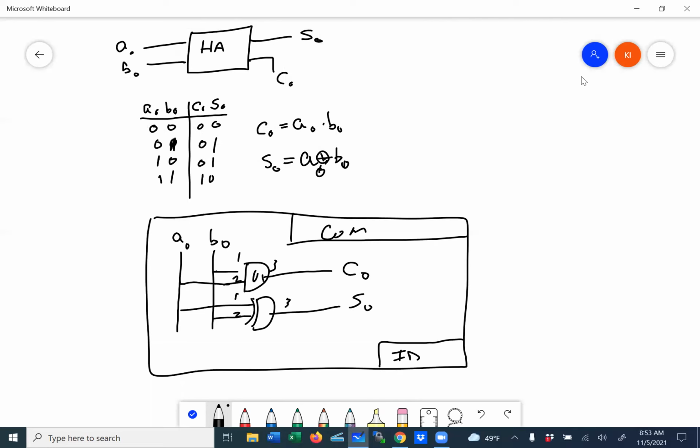And whatever, let's call this one U1 and U2. You're done. You basically have designed a half adder. You're done with that. The next step in the process is you do a full adder. Okay. And since now you know how to do a half adder, in the future, you don't have to draw what's inside the half adder block. You can just drop it into your circuit,